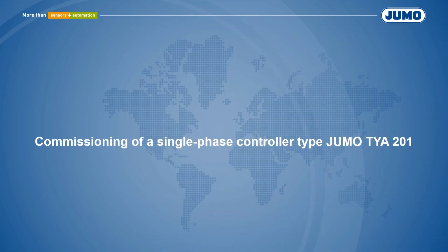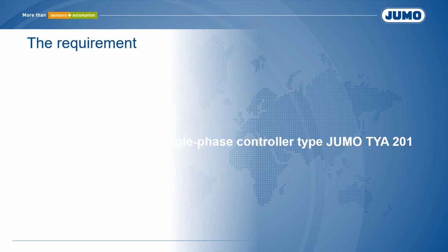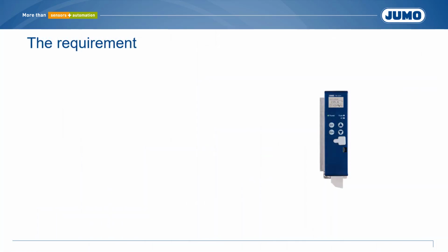In the following, the commissioning of a single-phase power controller is demonstrated. In practice, heating elements often have a nominal voltage equal to the phase voltage or phase-to-phase voltage of the respective low-voltage network. The elements are then operated directly via a Thyristor power controller on the low-voltage network.